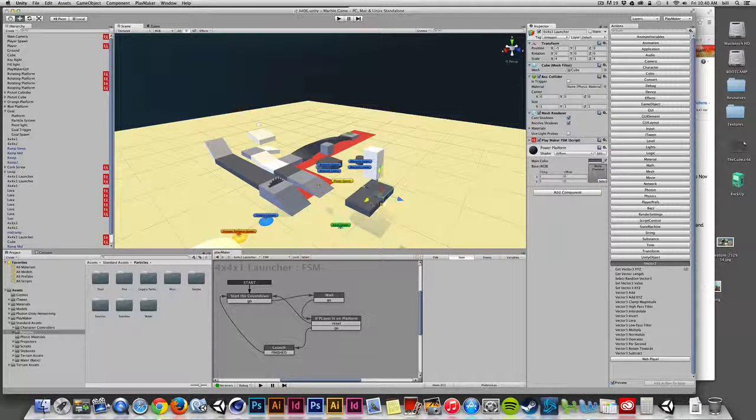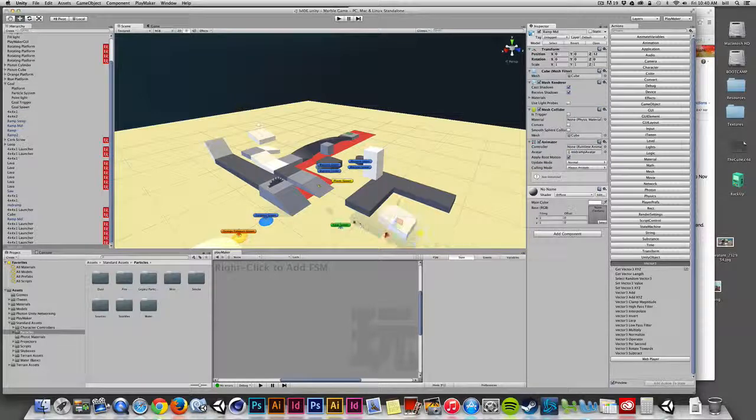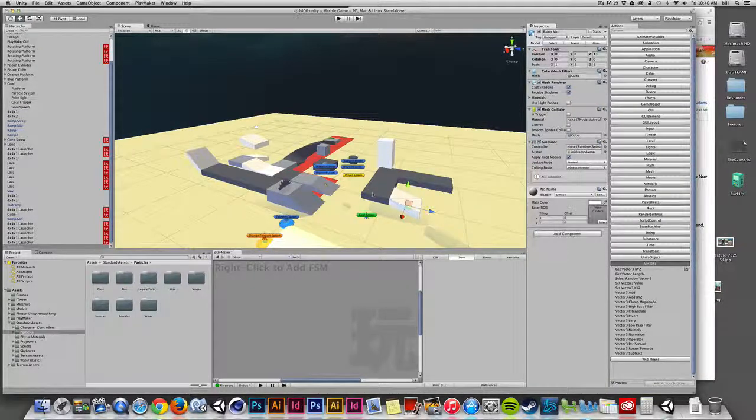with Command D to duplicate and then holding down the command key, we can quickly duplicate and snap these tiles together to create a platform, a level, and I can just grab different increments. Because I've modeled these elements based on 1 meter and they're 4 meters square, all of these pieces fit together.